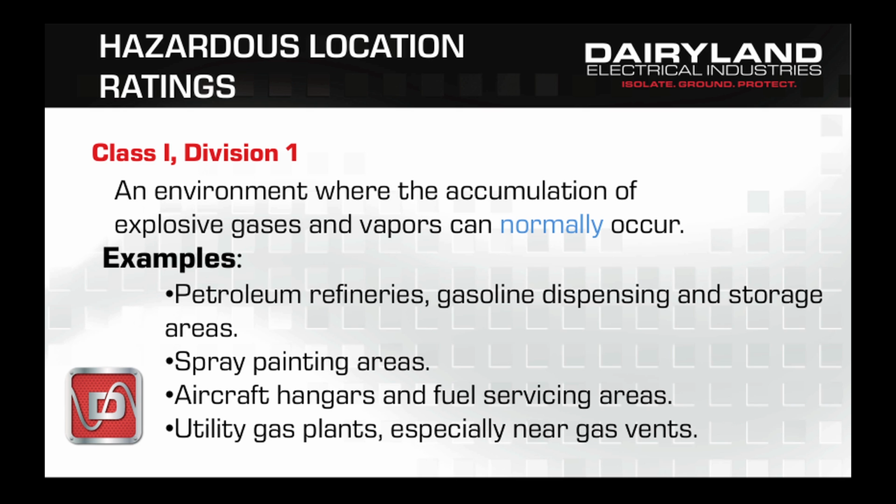Another situation I should mention is where electrical equipment is placed in a pit, where the accumulation of gases and vapors can readily occur. You should be aware that different companies interpret what is a gas venting area differently. Some would say within 8 feet of a vent. Others would have a different corporate policy, possibly more or less restrictive.